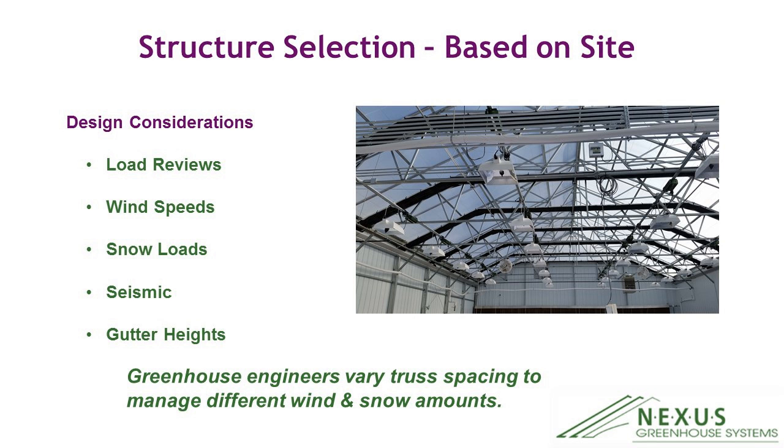And when you're selecting your structure, it's important to consider what you're going to have to withstand with the design of your structure. If you're in a very heavy snow load area, you're probably not going to want to choose a structure that has, say, a double poly roll plastic roof. You're going to want a structure with probably an A-frame and a hard, rigid covering that can really stand up to the snow loads. Same thing goes with wind, and same thing goes with the seismic levels.